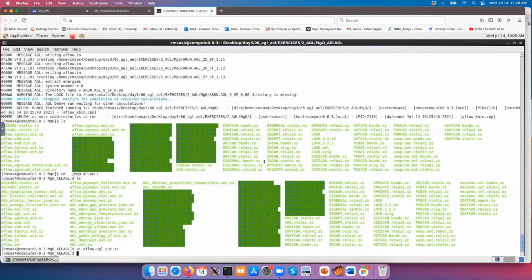And so it's roughly in the middle of the range. Most materials have a Poisson ratio between 0.2 and 0.3. There are a few that have higher or lower Poisson ratios, but all stable materials will have a Poisson ratio of less than 0.5 and more than -1. Materials with a Poisson ratio between -1 and 0 are quite rare; they're unusual materials. So pretty much all normal materials will be between 0 and 0.5, and most will be between 0.2 and 0.3. So 0.25 is usually a reasonable approximation for most materials. Okay, great. Thank you.